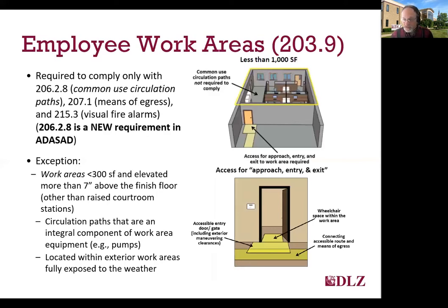One important area of facilities that is often overlooked and incorrectly assumed to not be accessible since they are not public, and the reason I'm doing this presentation today, are some areas open only to employees. There's really a lot of confusion out there on the part of many in both the industry as well as clients about what employee spaces are regulated and what the requirements are for access. Both sections 203.9 and 206.2.8 include provisions for employee work areas, with the provisions of 206.2.8 actually being new to the 2010 standards, and I'll discuss that in a little bit more detail on the next slide.